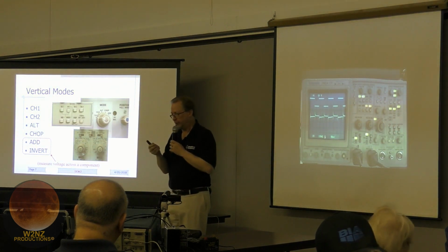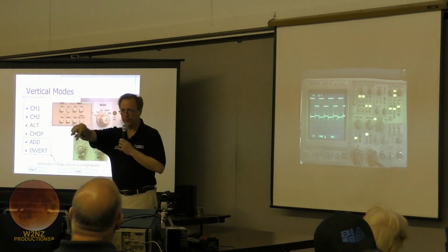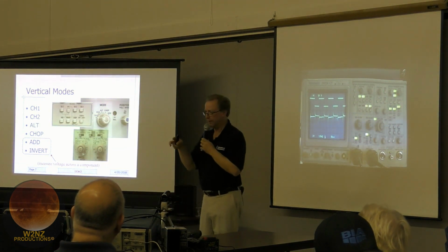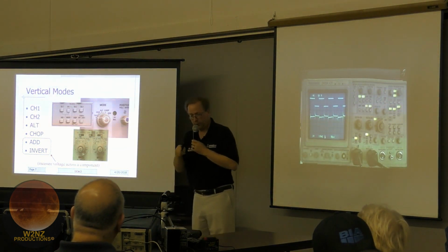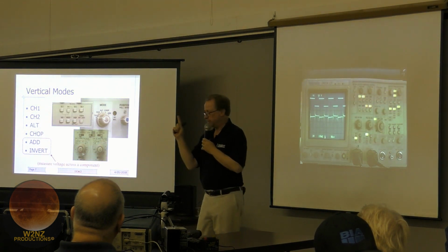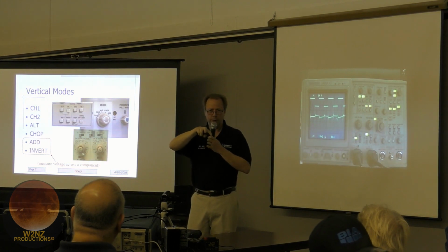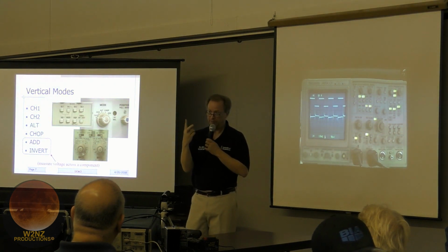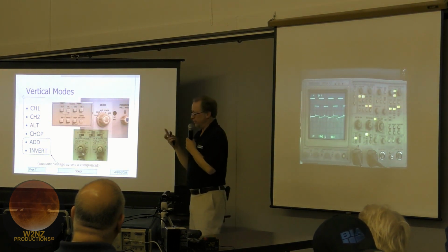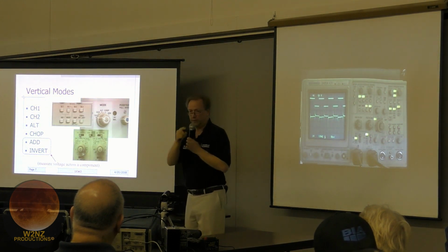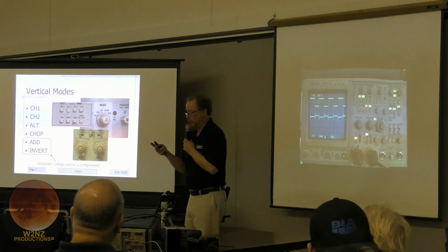Right? Because with a voltmeter, you can take those two probes and stick them anywhere. Stick them across the resistor, stick them across the transistor, whatever it might be, to see what's going on in that circuit. You can't do that with a scope probe, because a scope probe has got a single input and a ground. You can't clip the ground in any arbitrary place on the circuit because it's ground, okay? So in order to measure the voltage difference across a component, you basically connect to either side of the component with two probes.